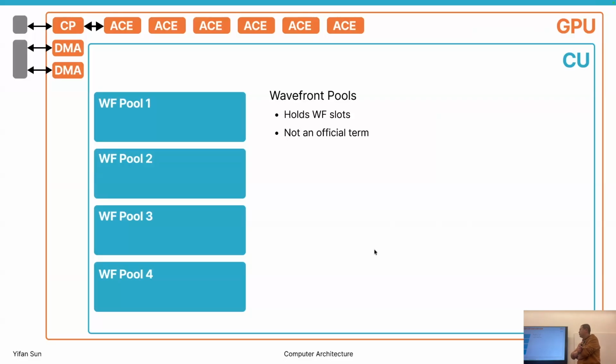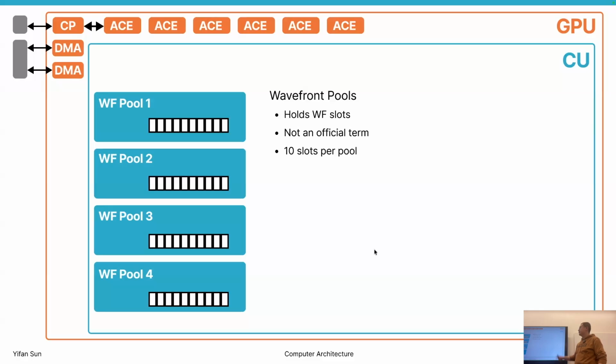Wavefront pools. Wavefront pools are where the wavefront slots exist. It's very interesting that wavefront pool is not an official AMD or NVIDIA terminology. It was made up by people while making simulators, and then it became commonly used. If you say wavefront pools, some people may know this term and some may not. It's okay. We describe a wavefront pool as a list of wavefront slots.